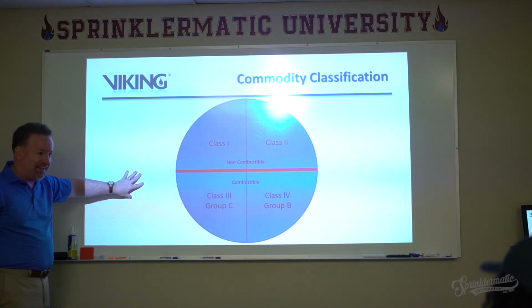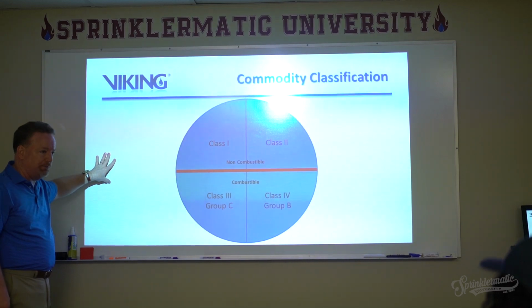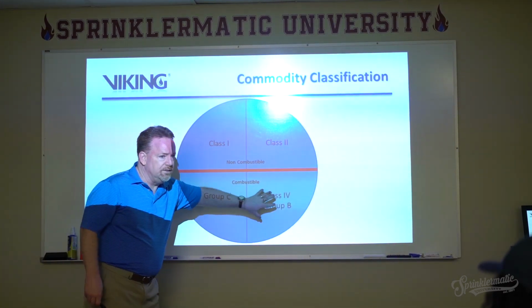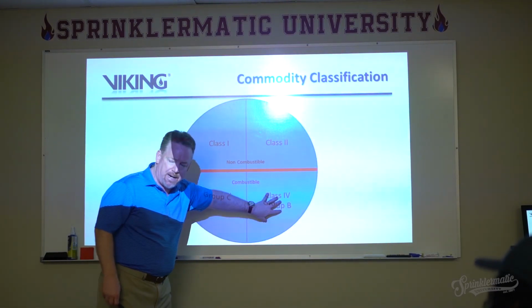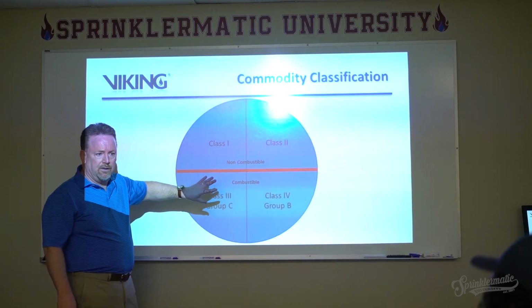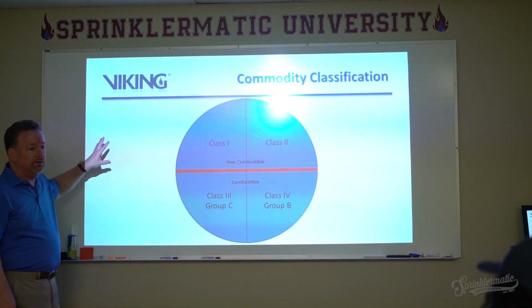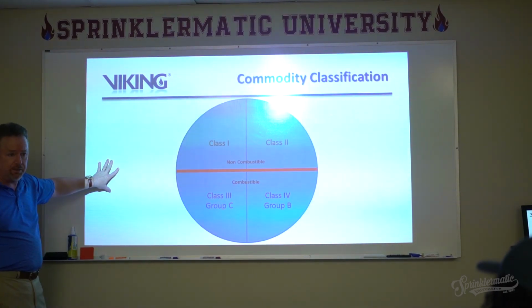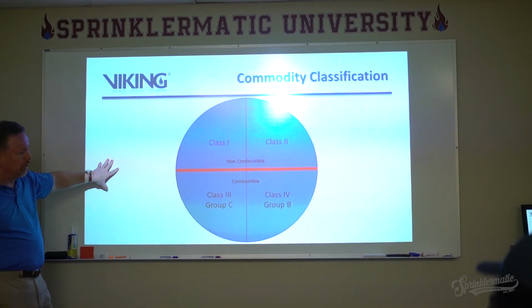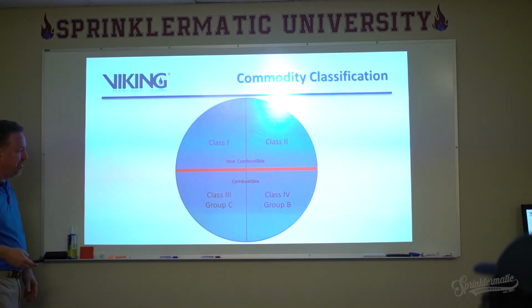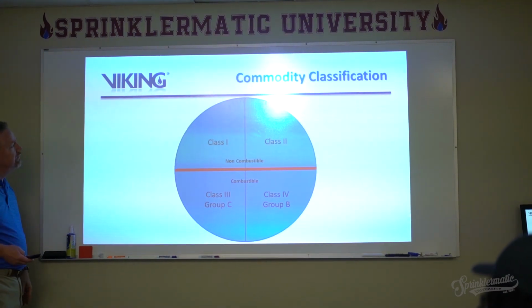The one thing that's not in here is the standalone Group A plastics. Remember that each one of these can have a certain amount of Group A plastics in it without being considered wholly Group A plastic to be protected. So these are the 4 basics, and then you've got the Group A plastic, the 5th one on the outside.